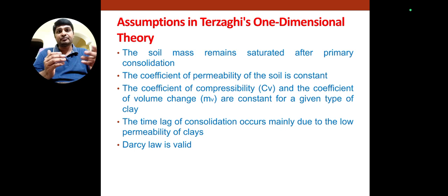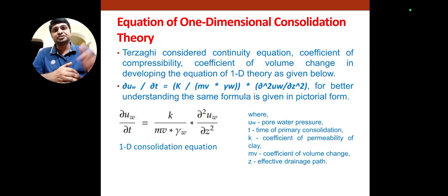The coefficient of compressibility and the coefficient of volume change are also constant for a given type of clay soil, because Terzaghi studied and tested a clay mass very well for the one-dimensional theory of consolidation process. The time lag of the consolidation occurs mainly due to the low permeability of the clays. The last one is that Darcy's law is valid. These are the assumptions of Terzaghi's one-dimensional theory.